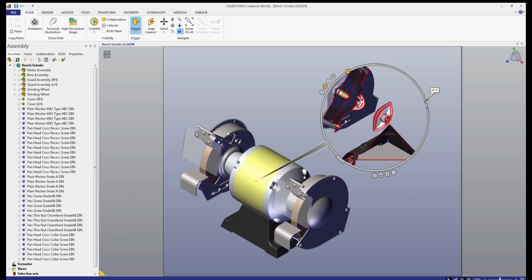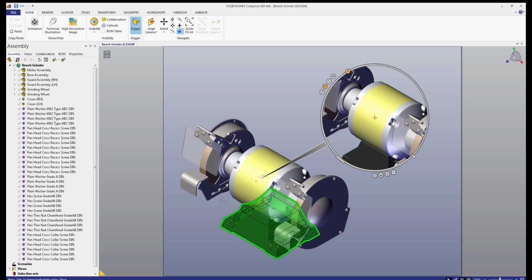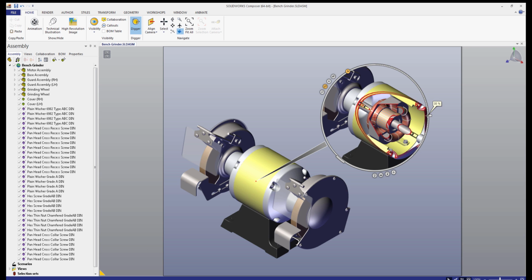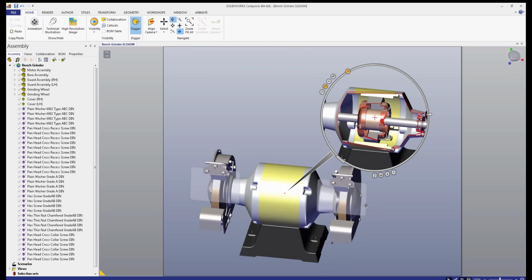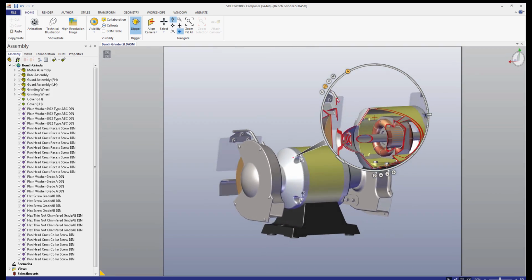This leaves the cutting plane. As you scale the slider up, this tool will begin to cut into your assembly at an angle determined by your camera orientation. As I increase the slider, you'll begin to get a sense of what this view looks like. Also important to note is that if I change my camera orientation, the cut changes correspondingly.